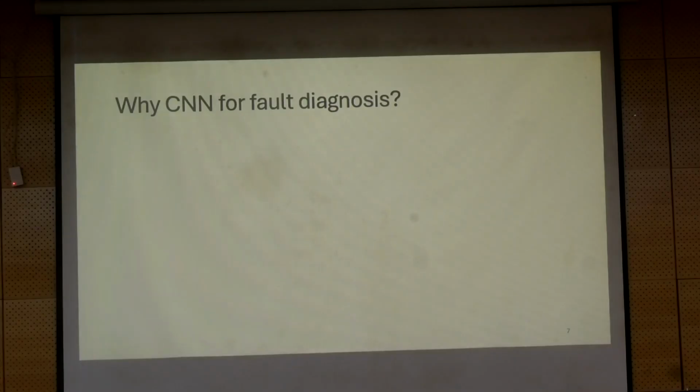So yesterday when you were brainstorming about the challenges, one of the key challenges that we found when we wanted to use an artificial intelligence method like ANN was feature selection. If you recollect the article that I shared with you, I have selected time domain features of my stator current such as RMS, mean, skewness, kurtosis, like that.